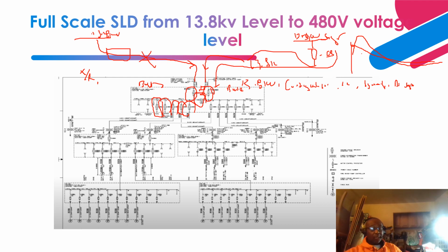Short circuit currents are going to be very high, and you need to have a current limiting limiter to be able to limit the amount of short circuit current, so that your switchgear design and equipment wouldn't be so expensive. These are all dedicated cubicles on the switchgear lineup, to be able to accommodate future expansion of the switchgear.